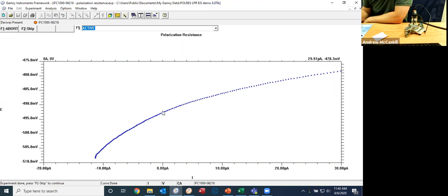But what you can do, by use of the Stern-Geary equation and having accurate Tafel constants, is figure out what this corrosion current is relative to the OCP value. If anybody remembers some of their more advanced mathematical techniques, it kind of comes back to perturbation theory. A small perturbation, let it come back to its steady state, and then try to figure out what the constants or values are relative to that steady state.